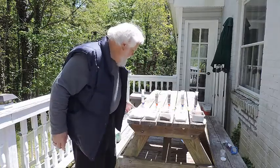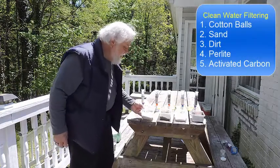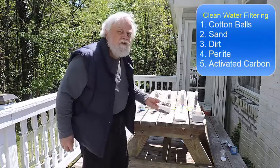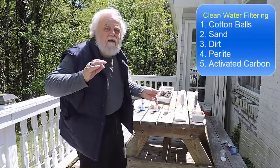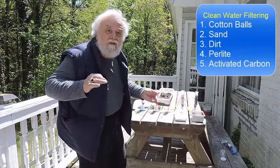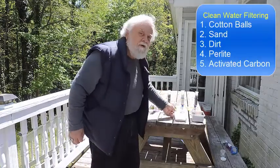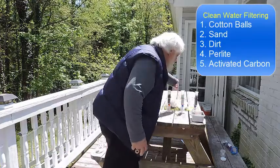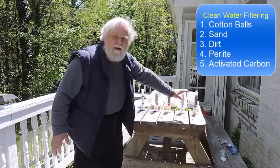The materials that we're going to use for our filters are not paper. The first one is ordinary cotton balls. The second one is ordinary sand. The third one is ordinary dirt. And believe it or not, dirt is very good at cleaning up dirty water. So dirt can clean dirt out of dirty water. The next one is a material called perlite, and it is a crushed volcanic rock. And the last material is activated carbon. Cotton, sand, soil, perlite, and carbon.